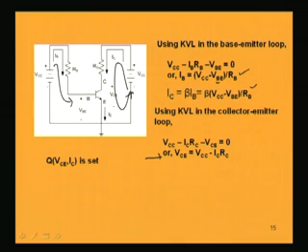Similarly, if I have a change in temperature, suppose the temperature is increasing while operating the transistor, then the collector current will increase because of the increment of the leakage current ICO. So, again that IC will increase, which means VCE will also be affected. So, whatever Q point I have set, it will now be shifted again.